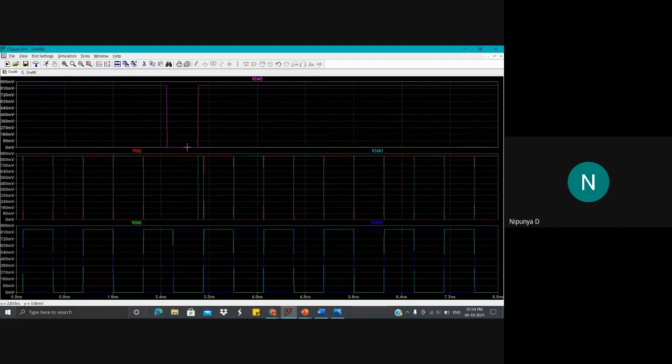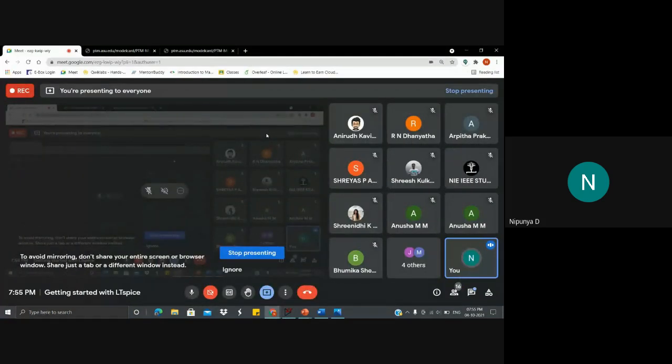When it is in hold state and then it switches back in order to accept the responses into the latch, exactly at that point you are able to see a glitch. So it is caused due to the switching of the word line from hold state to read or write mode. That is why you will be able to observe these glitches. If you look at some other advanced SRAM technologies, by increasing the number of transistors or other ways, you will be able to avoid those glitches. Since this is a basic model, you will tend to see those glitches in the picture.